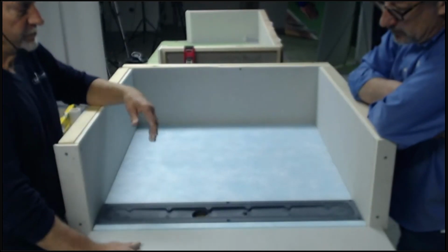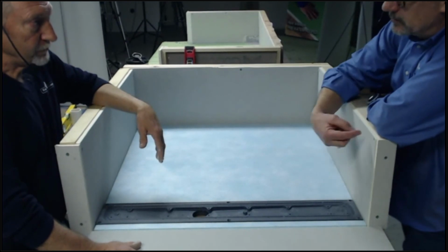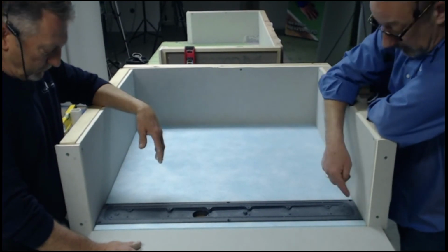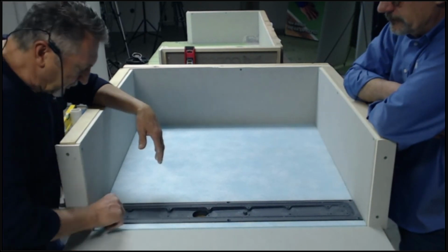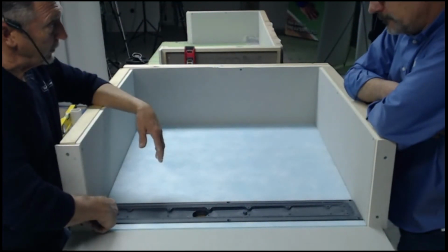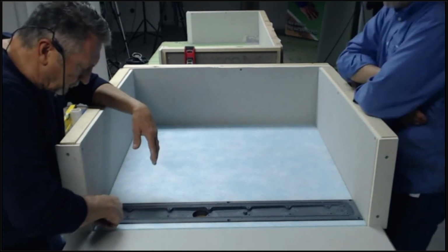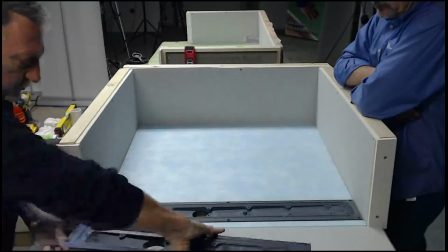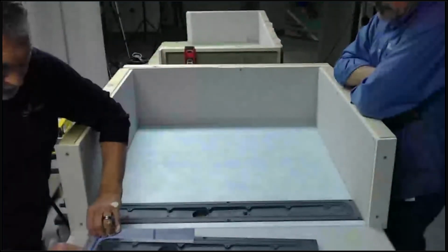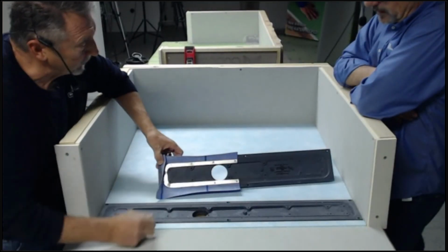Right. Now, this drain, you could run this drain, depending on the situation, directly to the plate essentially, so that when my board was coming down the wall, it would really fill the gap right here. So it's almost overlapping the drain. You can, because your strainer is about 3/4 inch back from the body. So it really flushes out almost perfect with the tile. So you could, and then you upturn right directly, as you can see, right directly at the clamping ring. Yep. It's over here, and upturn just like that. Right. At your backer board.